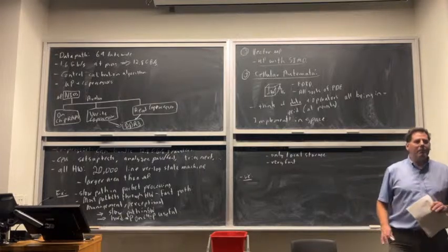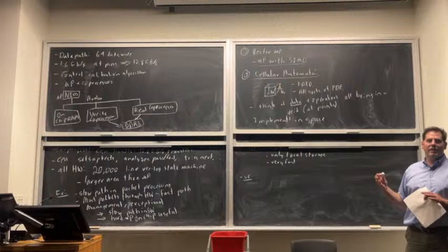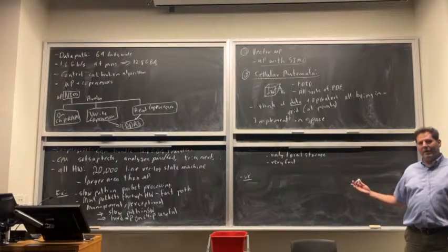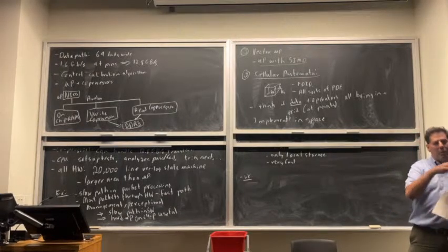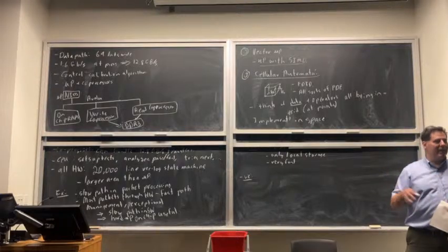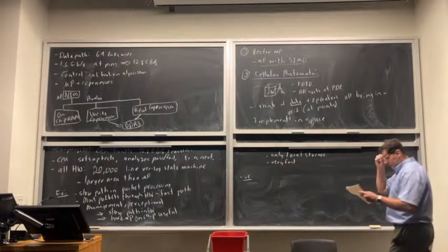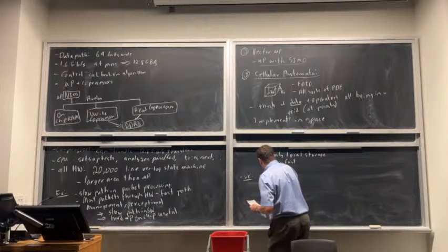But the physics simulations that you want to speed up tend to be big. That means they have big grids with thousands or tens of thousands or millions of points. If every point goes to a specific spot on the FPGA, it's extremely efficient, but you hit big problems, you just run out of space. You need an extremely big FPGA. So the negative is you run out of hardware for large grids.